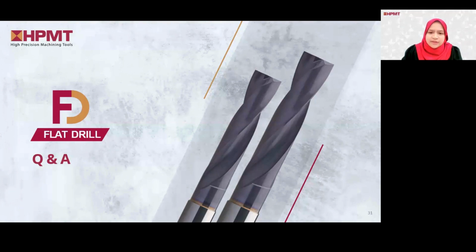So for this one, we do have an encounter with a negative issue before. For example, increased wear if it is not used properly, due to the heat generation during drilling. So the solution for these negative issues is we have to ensure proper alignment and secure the drills before use. Besides that, we also need to use appropriate cutting speed and feed. I hope it answers the question.